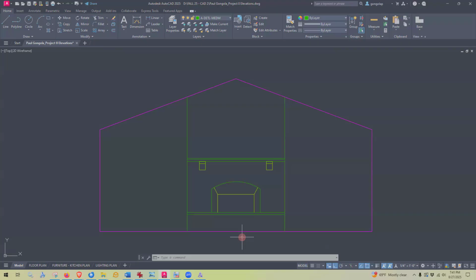So again, the command is save time and then just set it to whatever. You can set it to 1 if you want. And the only reason I don't set it to 1 is because every minute I get this message here that says your drawing has been autosaved. And you'll see it in 2 minutes, you'll see it come up here. But if you want 1 minute, go for it. It's fine.